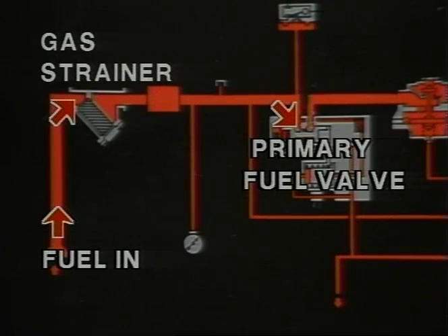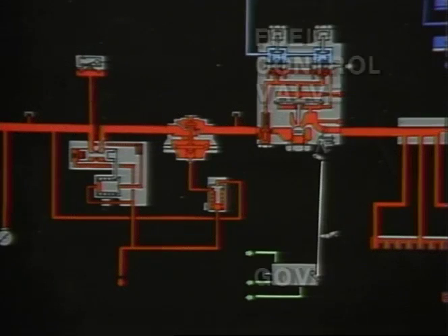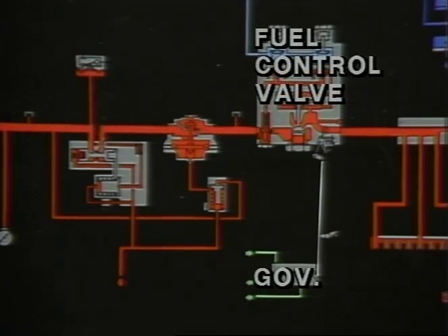As the engine begins rotating, after initiation of start, the governor actuator receives an electrical signal to move the throttle valve to the full open position. Up until 90% speed, fuel flow is scheduled by the fuel control valve, not the governor.